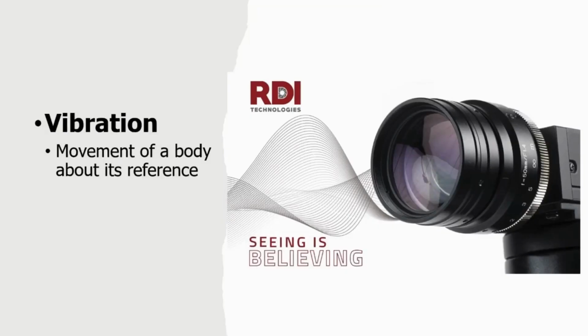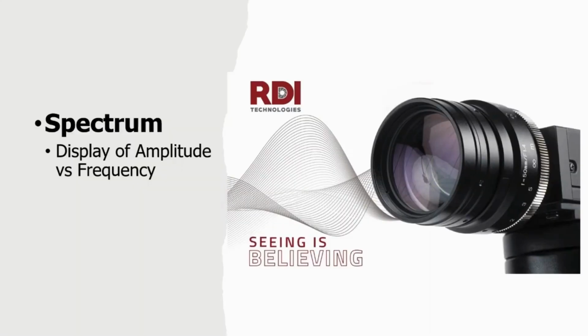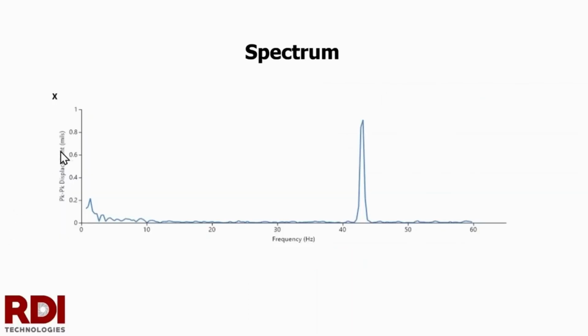The first term I'd like to define is simply the word vibration, which means movement of a body about its reference. So when we look at a spectrum, a vibration spectrum, which of course is a display of amplitude versus frequency, we see two scales. We see a vertical scale on the left-hand side, which is our amplitude, and we see a horizontal scale on the bottom, which is our frequency.